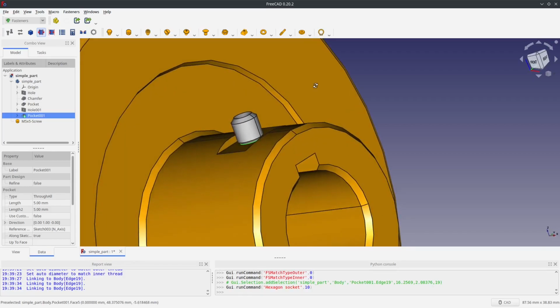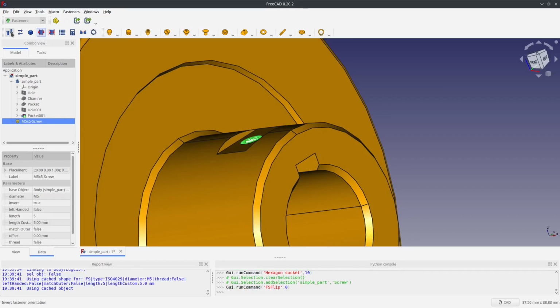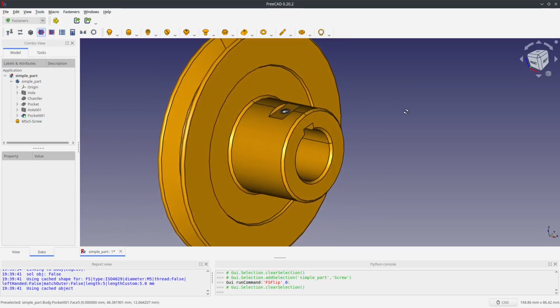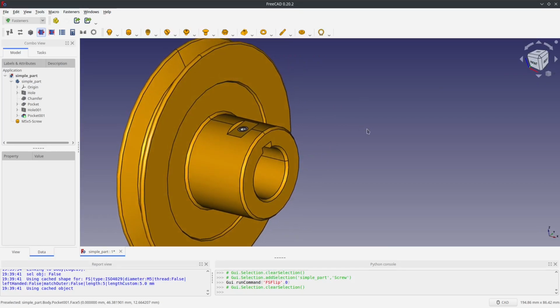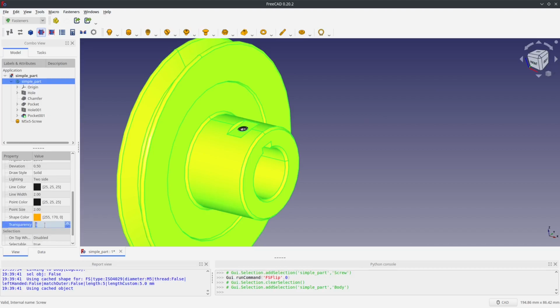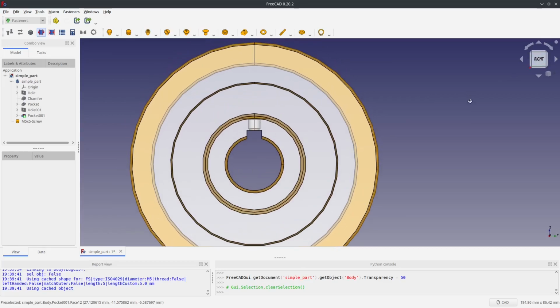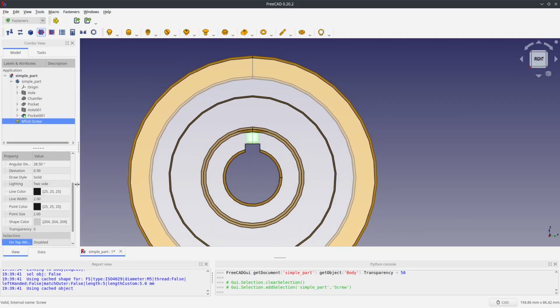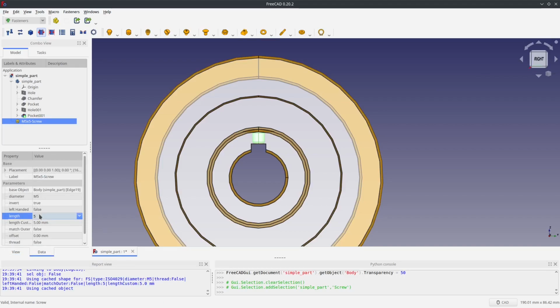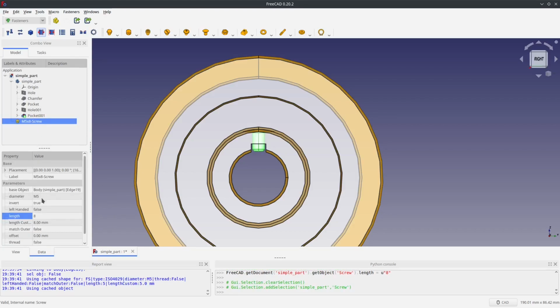If I want to change the properties of an existing screw, I can select it in the 3D or tree view, then use the Properties Manager panel to update the length or the diameter or the type of the fastener. By default, standardized lengths are used, so they're available in discrete increments, but I can also specify custom length fasteners by switching the enumeration property to the custom option. Just keep in mind that fasteners that have a custom length aren't necessarily going to be available as off-the-shelf parts.